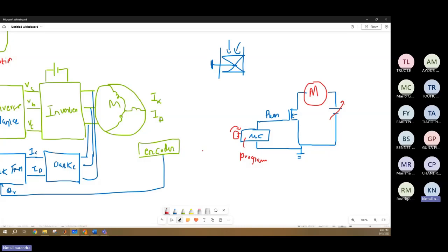With this, I can program this microcontroller and I can control the switching of this MOSFET. Once I know how to control the MOSFET, I'm able to control the speed. So when I go on uphill, if I need high speed, I'll detect the uphill by using a camera, and I'll tell my microcontroller, increase the PWM. Then it will increase the current. Then the vehicle will maintain the same speed limit.